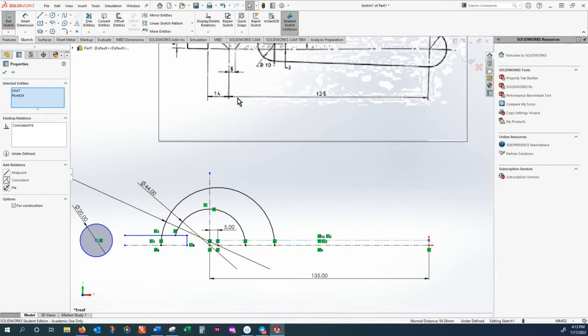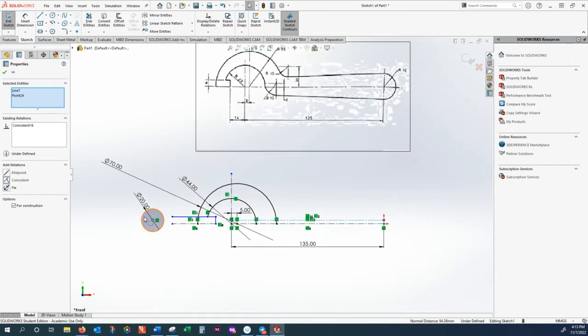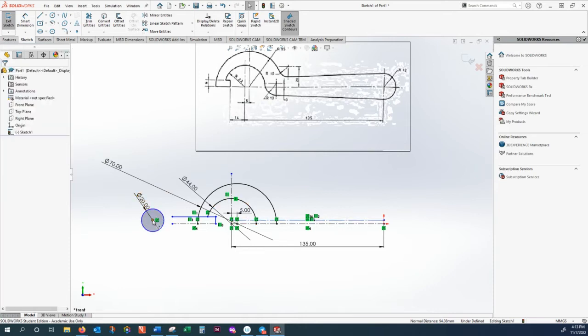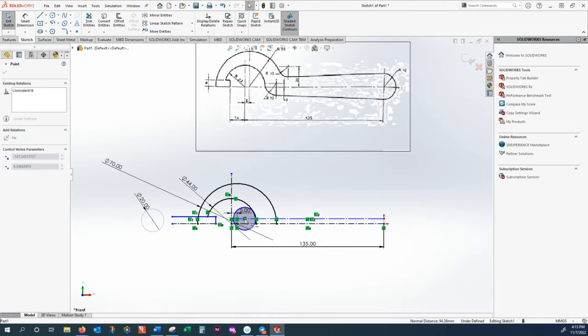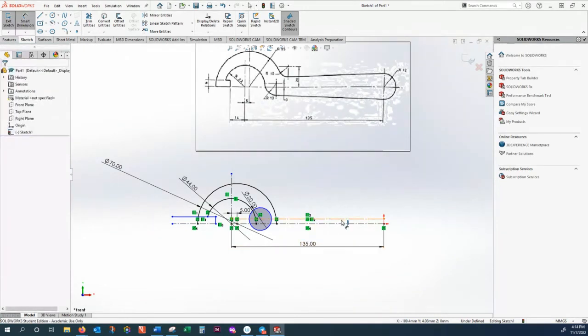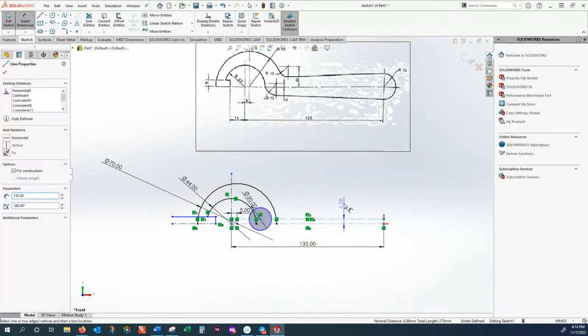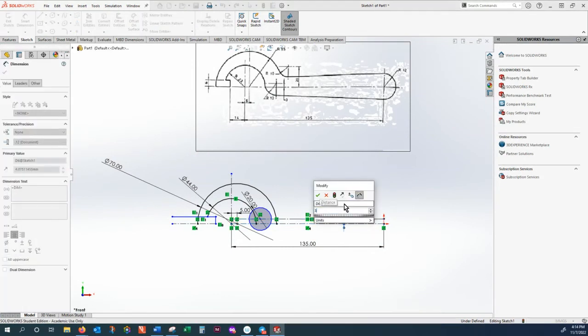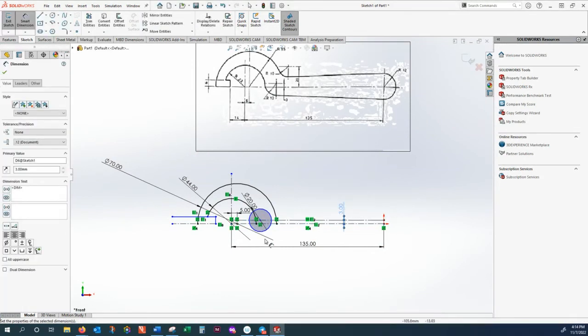And the next condition I want to add is make this circle tangent to that circle. But before that, just to avoid some things, okay. So that offset seems to be floating. I want to make sure it's specified. So let's make that 3, preventing this from change. All right. Now the next thing is that circle here.